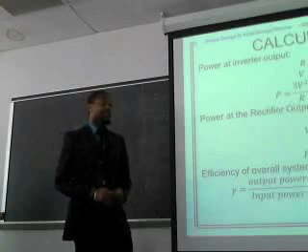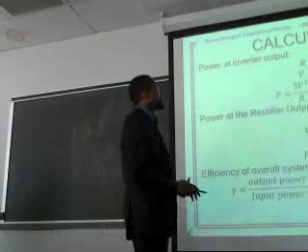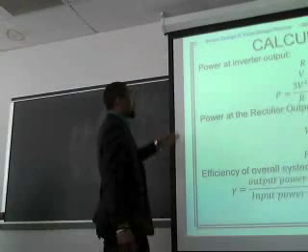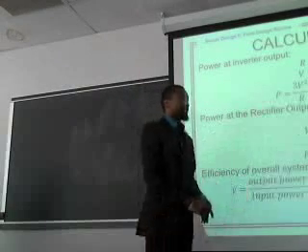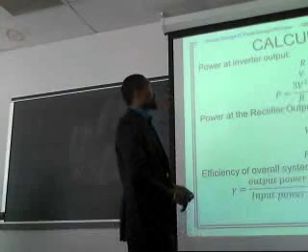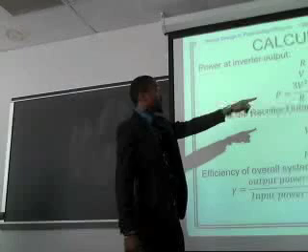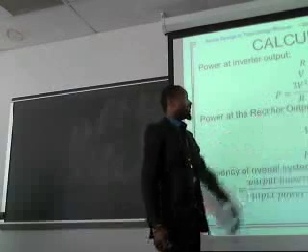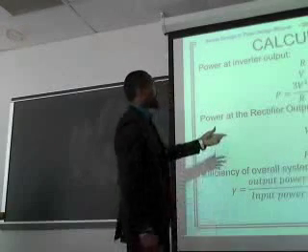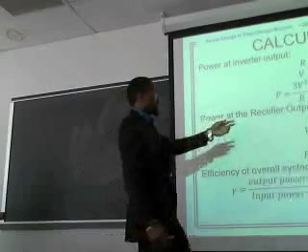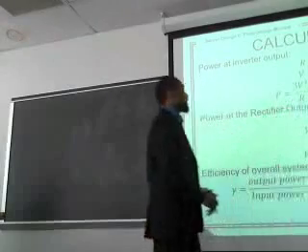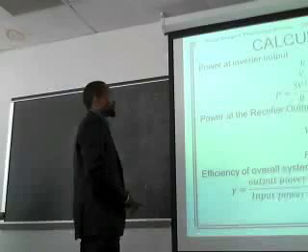And then we did the calculation of how we came about the efficiency. For the inverter circuit, we use a 70 ohm resistor. Then the voltage, which I showed you right there, is 106 volts. To calculate the power, I take the voltage squared over the resistance, and we have this result right here, 481.5 watts.